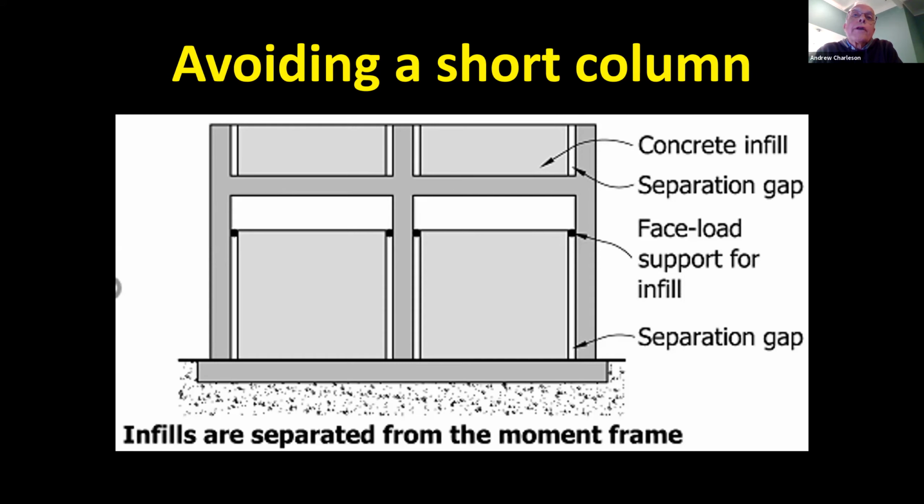to cover the gap and make it waterproof. Or you could cover the gap with some type of metal flashing, seam. And so those are the normal ways that architects deal with these gaps.